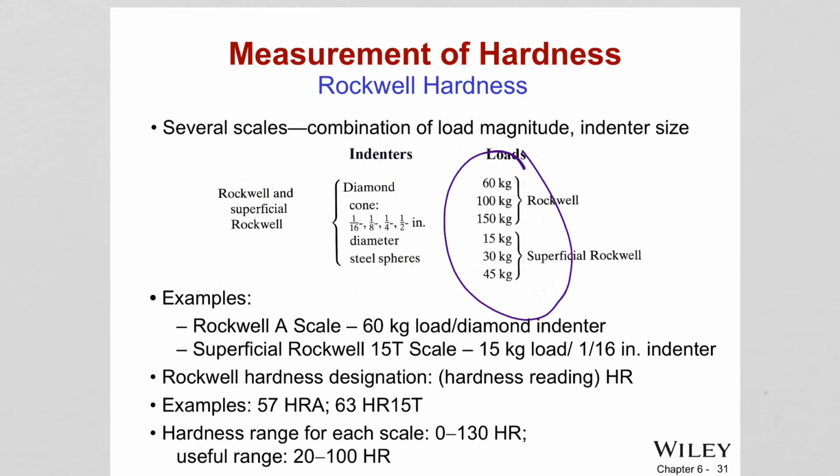In reality, this hardness value is not exactly a representation of what hardness is; it doesn't have a physical meaning. It is just a made-up equation to relate the measured indentation parameters to a hardness value. That's why different types of hardness tests use different equations to obtain a hardness number. So you just call it a number.